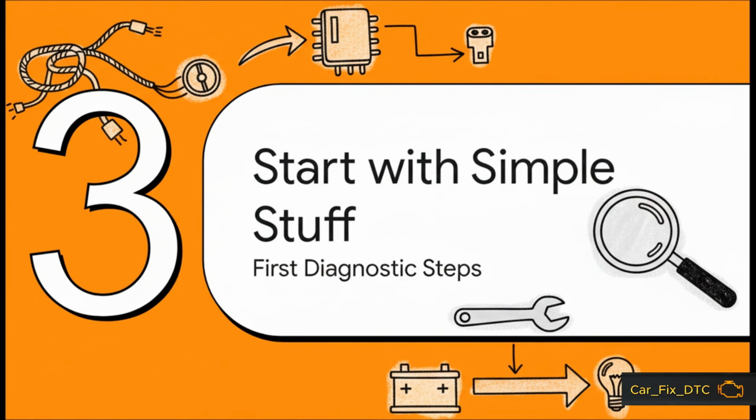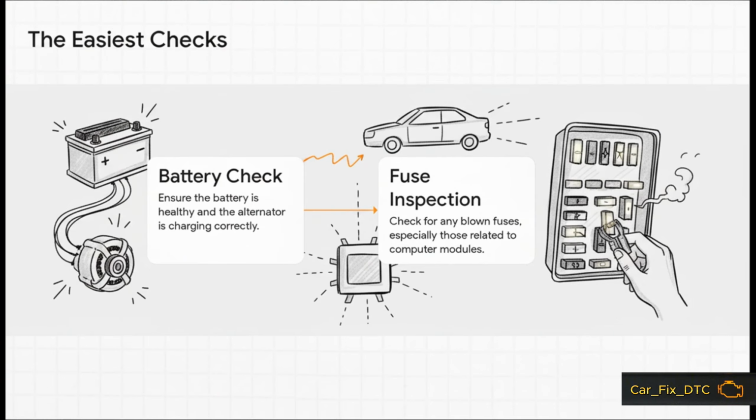All right, so where do we even begin to diagnose this mess? Well, like with any really complex problem, the number one rule is always the same. You start with the simple stuff first. And honestly, it does not get any simpler or more important than these two steps. Before you even think about complicated wiring or bad computers, you have to check your car's power supply. That means the battery, the alternator, and all the fuses and relays that go with them.